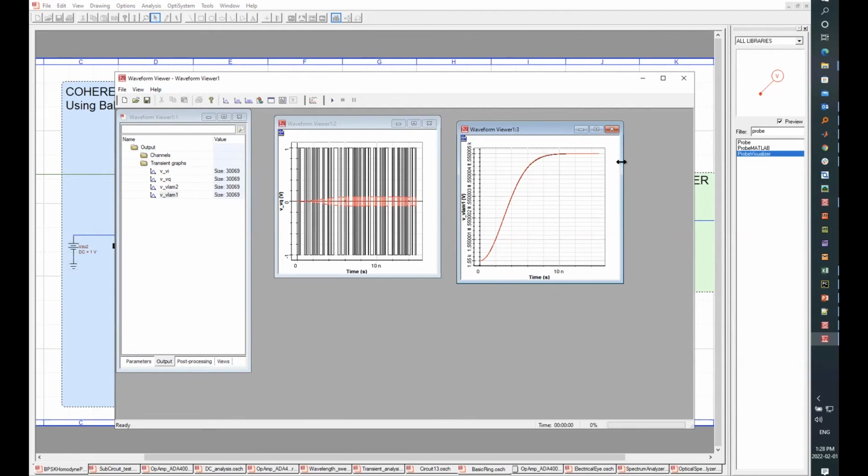We're also working with various fabs to develop PDKs. How that works is that we take their optical device measurements and specifications, and we make sure that we map them onto the devices that OptiSPICE knows and recognizes. When you work with a fab, for example, we have one with HHI, you can get access to Tanner and the PDK. HHI is a PDK for Tanner, and we have an optical device library for their PDK.